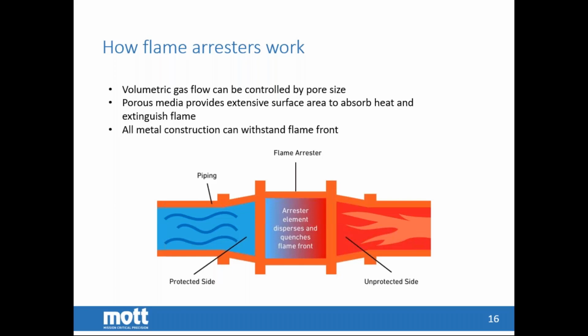Of course, if there is an issue where the flammable gas is exposed to the circuitry of the electronics, you run the risk of an explosion. And the porous metal flame arrestor is used to make sure that if there is that issue, the flame does not propagate outside of the sensor enclosure.